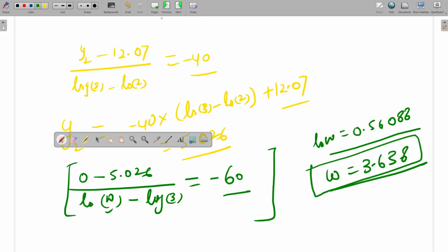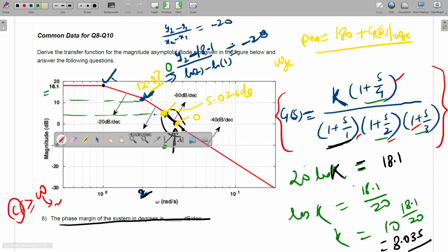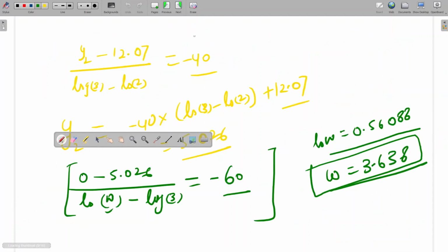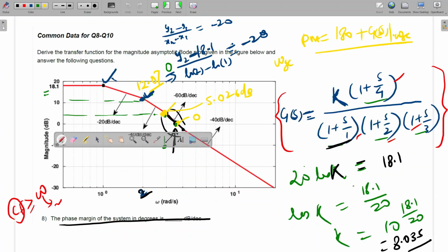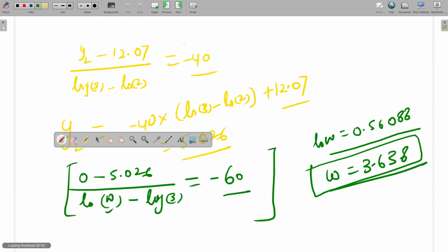Let's say this Bode plot was there now. So like this they will give the question, and this will be given. Then no need to solve this cubic equation. Directly we can see the Bode plot, and we can find the zero crossing magnitude frequency. So this explanation is clear to all? How I have calculated both the methods. Is it clear? Yes, sir.